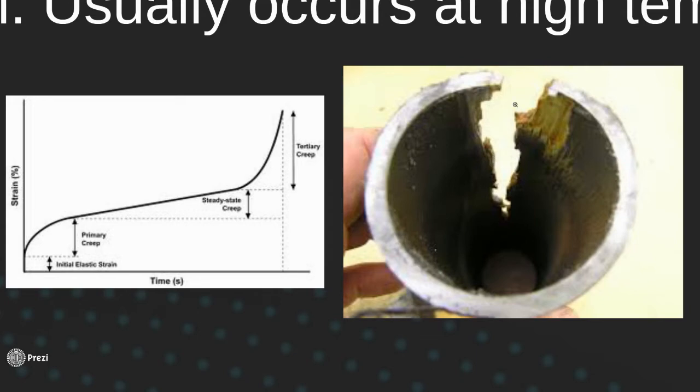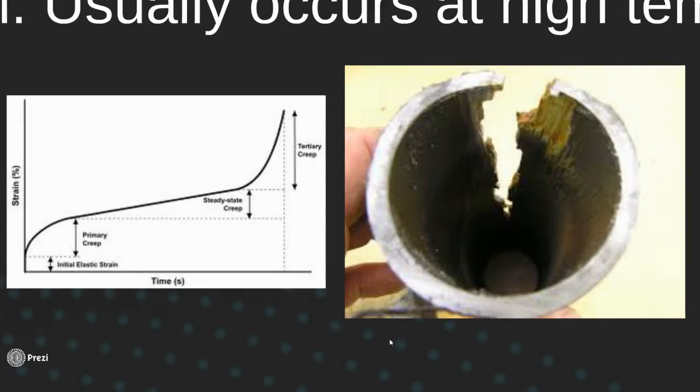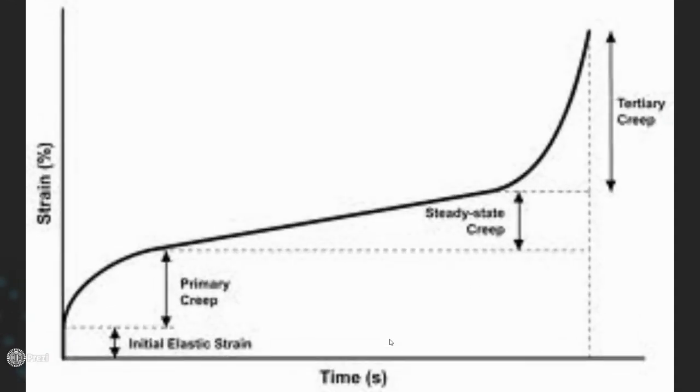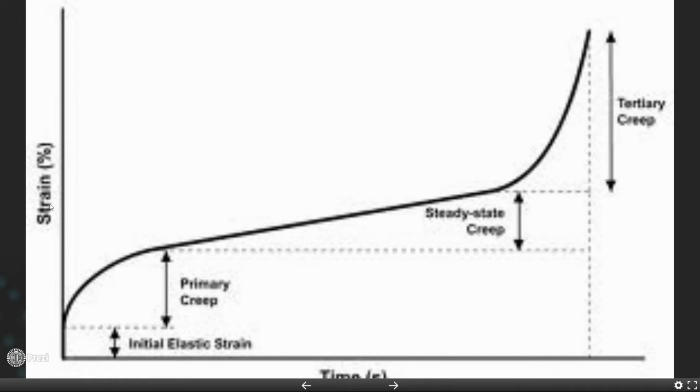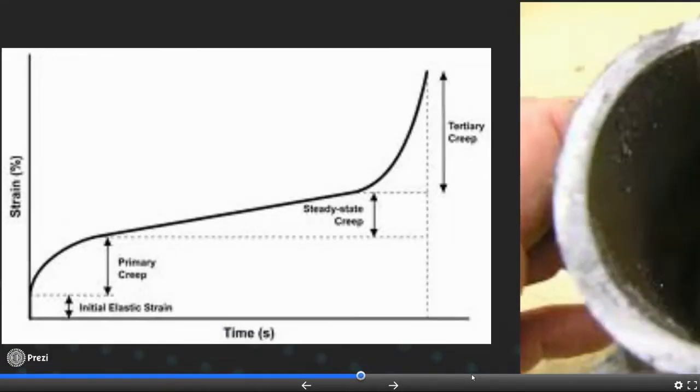In a power plant, these tubes have steam at extremely high temperatures and pressures. So when that weak point let go, there were explosions and people died. There was a big, huge investigation, all because of creep, and because they did not account for that. This is just another graph describing how creep works. I'm not expecting you to memorize this. Strain, remember, is how something elongates or stretches, which is what happens with creep. Over time, under sustained temperatures, you'll have creep, and then at a certain point, boom, that creep shoots up, and usually you'll have failure, even though it's underneath the yield strength.